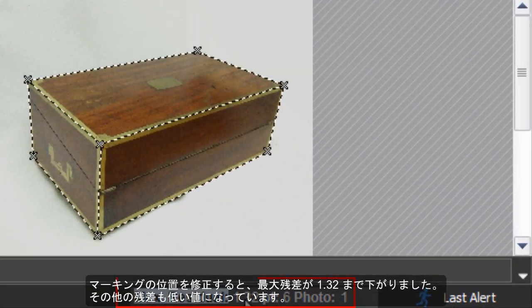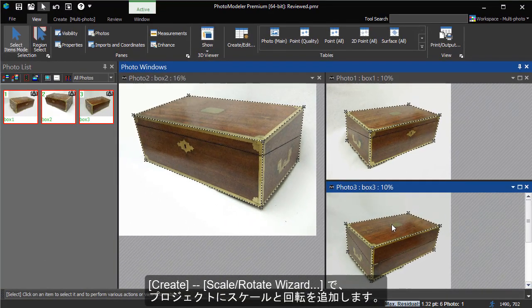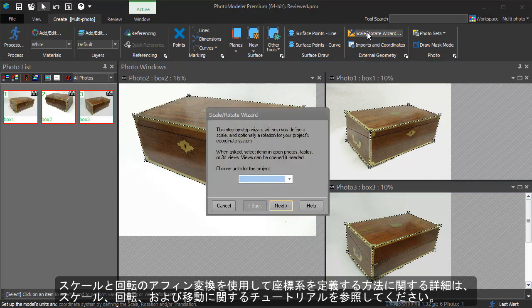After checking the placement of our marks, our largest residual is down to 1.32. The rest of the residuals are also low. We can now add a scale and rotation to our project using the Scale and Rotate wizard. For more information on defining the coordinate system using a scale and rotate affine transformation, see the Scale, Rotate, and Translate tutorial.